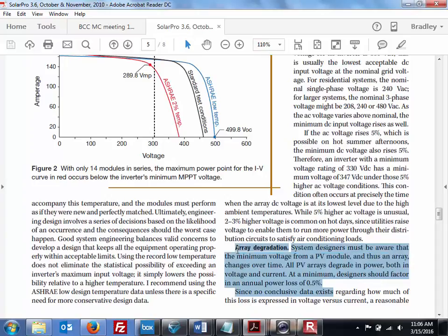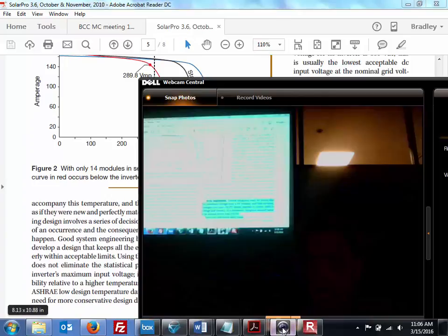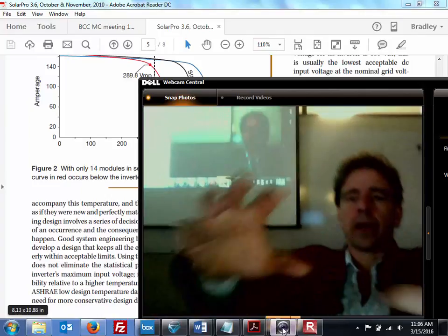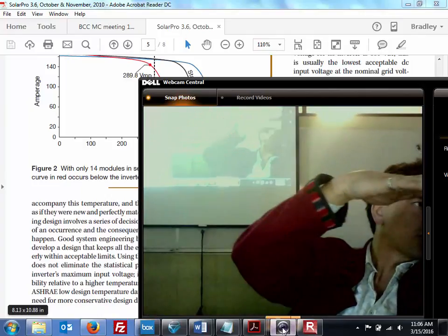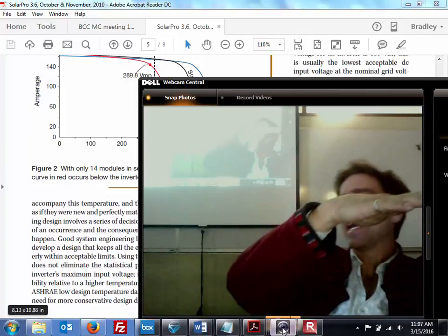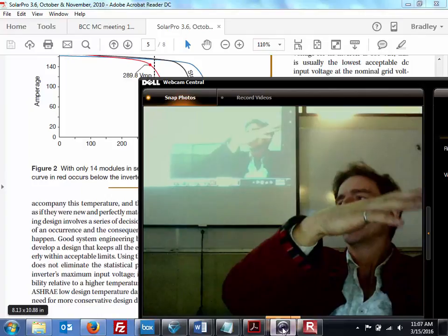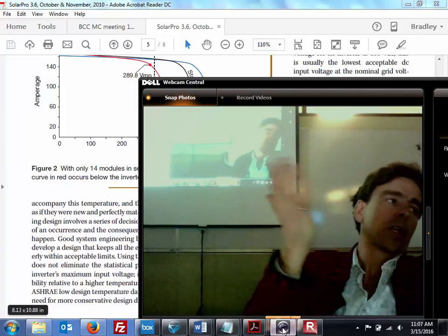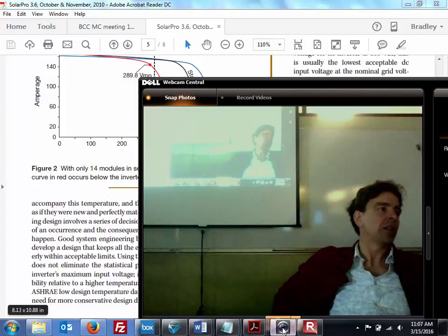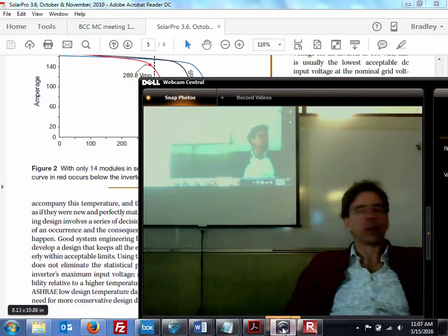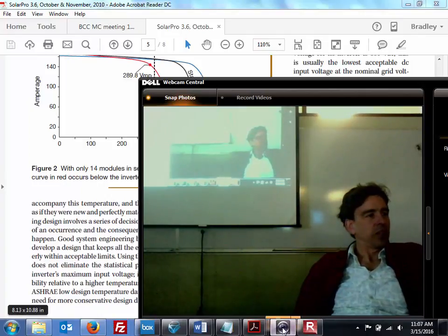Yep, it is. And really what's going on inside, and we've talked a little bit about how the individual crystals of silicon are aligned. Anytime you've got a material that's undergoing some kind of thermal cycling, hot, cold, it cracks. There are no self-healing silicon panels that I know of yet. Maybe somewhere down the road. There's a Dutch engineer who just came up with self-healing concrete, where he's got a bacteria that lives in there and secretes calcium carbonate that puts the thing back together. But we do not have self-healing PV panels.